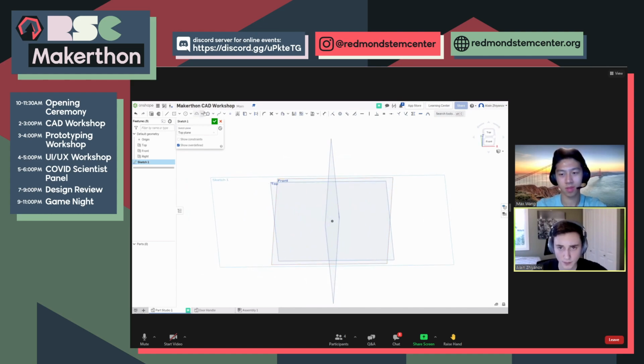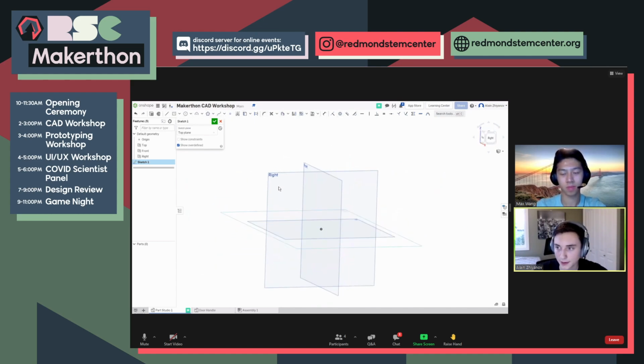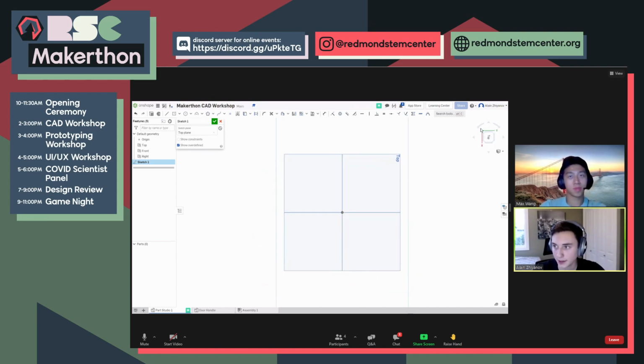As you see, there are a lot of tools up here. We have the same navigation as we had earlier in the 3D part of the Part Studio. And we have a sketch that pops up here in our feature tree. So the first thing we're going to do is get a line for our sketch. That means going normal to your sketch, which you can do by pressing N on your keyboard, and you show up on the bird's eye view of your sketch.